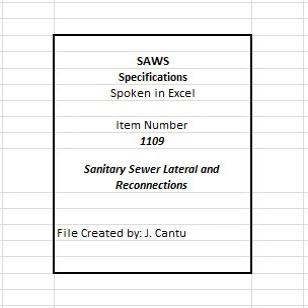A. Install lateral connections on the sewer main. B. Remove and replace cracked, offset, or leaking lateral for up to 10 feet, measured horizontally, from the center line of the sanitary sewer main. C. Make up the connection between the main and the existing lateral using PVC sewer pipe, with approved couplings, as shown in the contract documents.